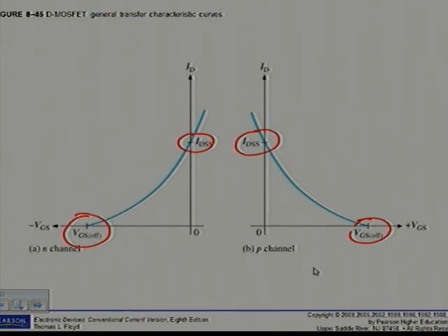The third one, the assembler's or the handler's wrist should be connected to a commercial grounding strap, which has a high value series resistor for safety. The resistor prevents accidental contact with voltage from becoming lethal. The fourth one, never remove a MOS device or any other device for that matter from the circuit while the power is on. And the last one, do not apply signals to a MOS device while the DC power supply is off.